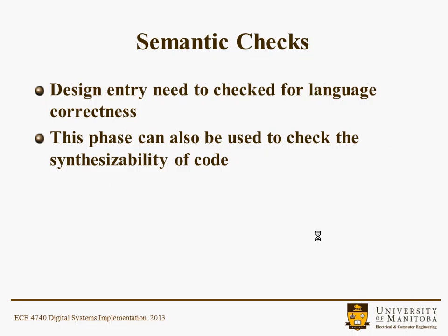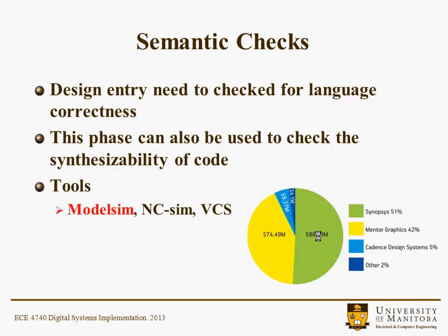At this point in time, there might be some need for semantic checks, just making sure the language is correct. This phase can also be used to check the synthesizability of the code. So it's one thing to have code, and it's another thing to have code that you can actually synthesize into hardware. Some of the tools that you'll use for this will be ModelSim, NC-Sim, or VCS. Those are industry standard tools. And over here it gives a good idea of what the big players in the industry are: Synopsys, Mentor Graphics, and Cadence.